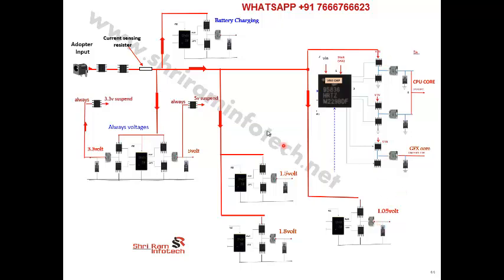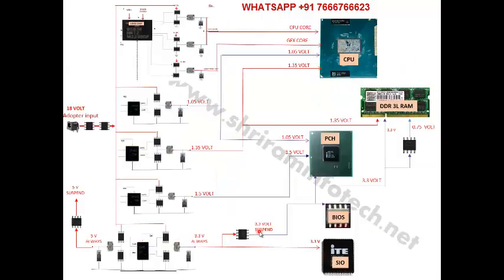So how much is the input voltage here? 18 volts, and the output voltages are different. Different coils have different pulse width modulators. So this is the concept. This is the entire circuitry of the laptop motherboard. Now in this section we'll see where this power goes.